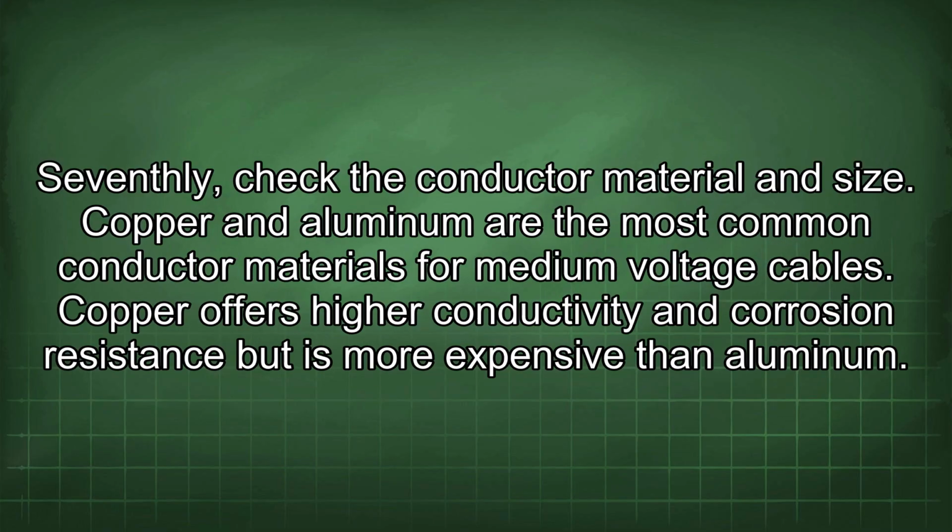Seventhly, check the conductor material and size. Copper and aluminum are the most common conductor materials for medium voltage cables. Copper offers high conductivity and corrosion resistance but is more expensive than aluminum.